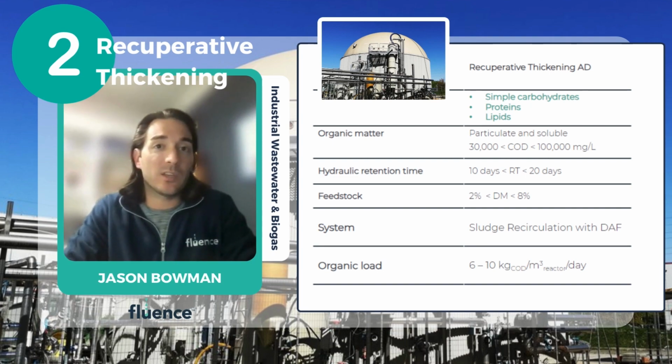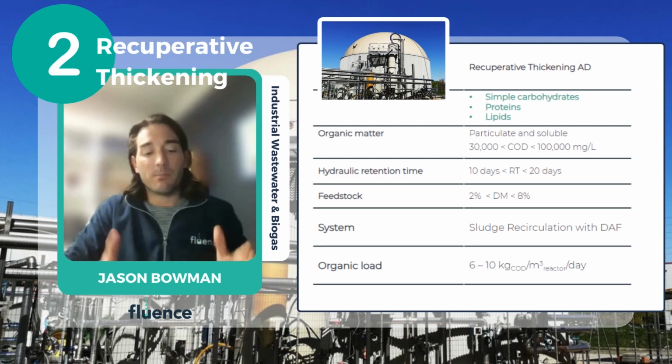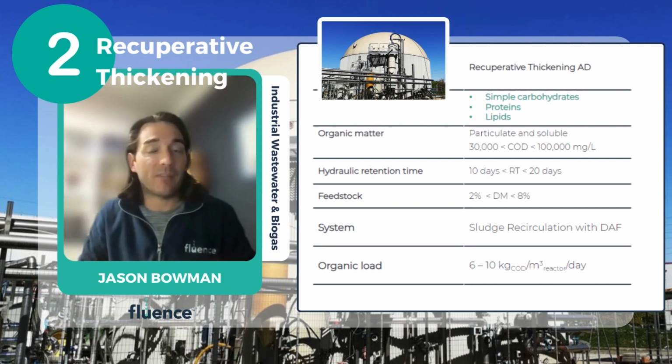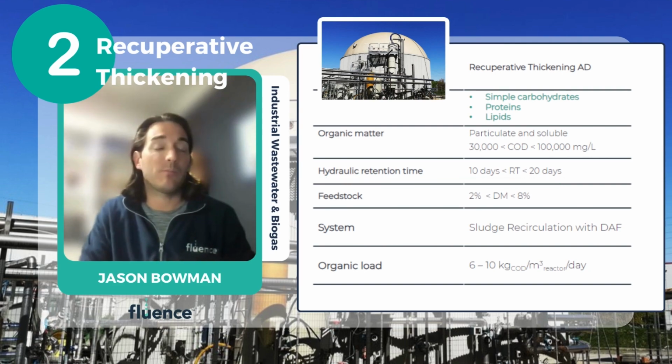In other words, every 1 part of solid that leaves the system, we can actually grab this, collect it, and recirculate it back to the system multiple times, 2, 3, 4, 5 times if we wish. So in this way, the mass of bacteria comes into contact with the waste more often. And we don't have to have as high of an HRT for this to happen. So that's what I mean by the SRT and the HRT being decoupled in this situation.